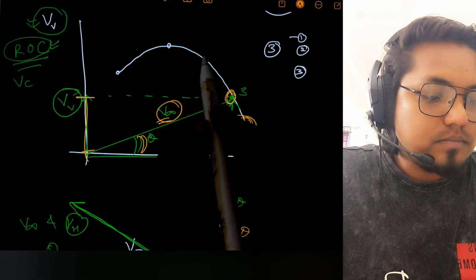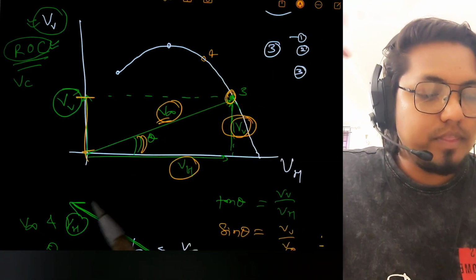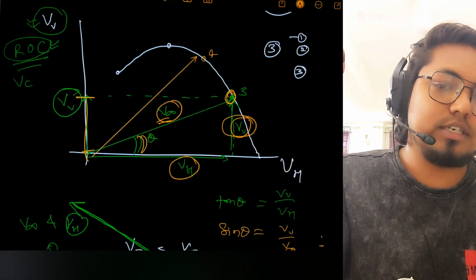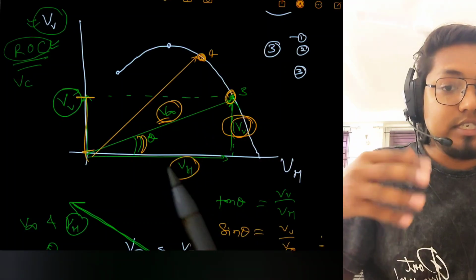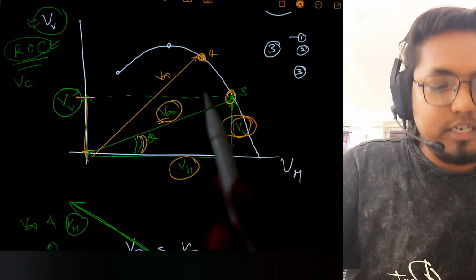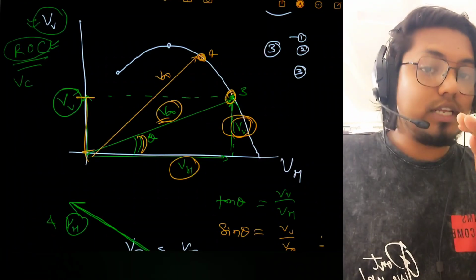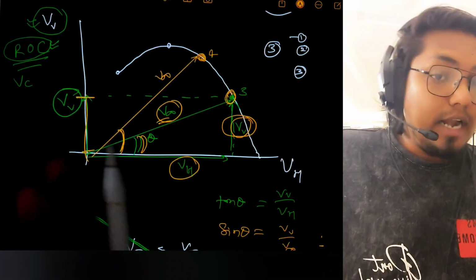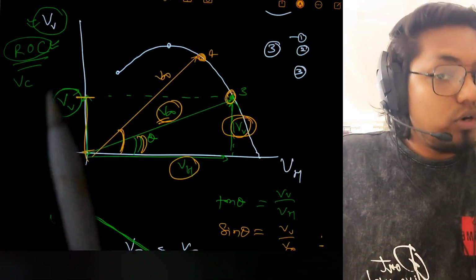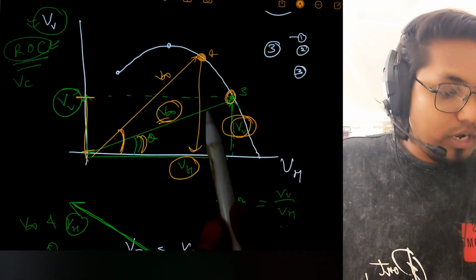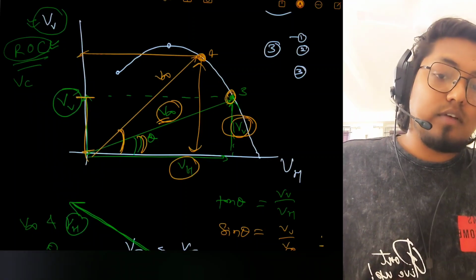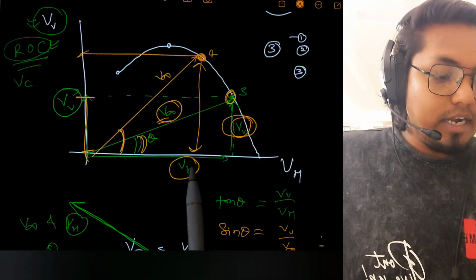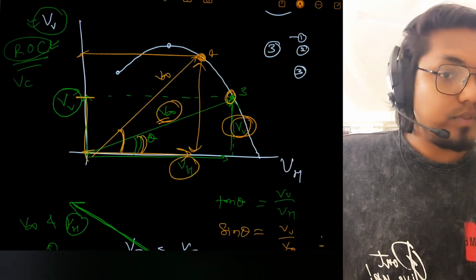Now if I switch to this point here, suppose this point is 0.4, then what will happen at 0.4? I will change this connection here from origin to this, correct? Now this 0.4 is telling me what? Now this became a new v infinity, a new velocity at which aircraft is climbing. But again, one more information, a new theta also, a new climbing angle, and two more new information. That time you are having this much vertical velocity, means rate of climb, you can see, increased, correct? And you can also see your horizontal velocity decreased. I hope you got it.